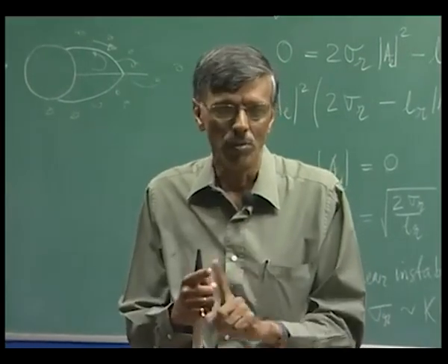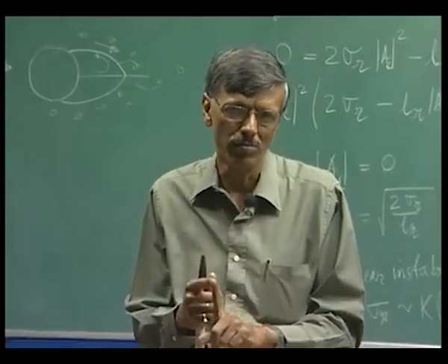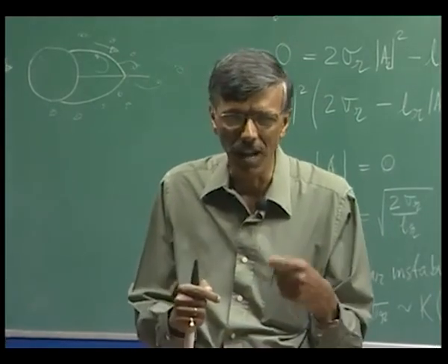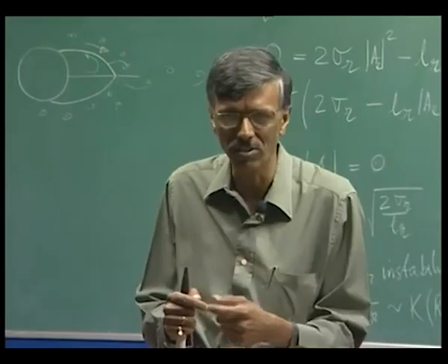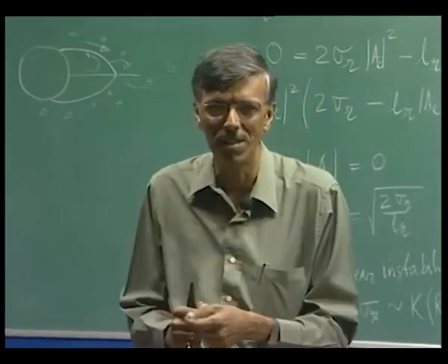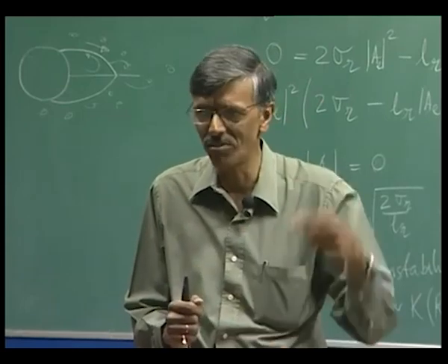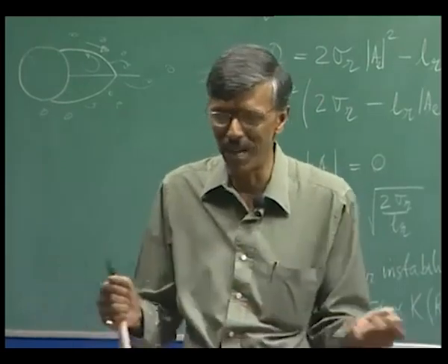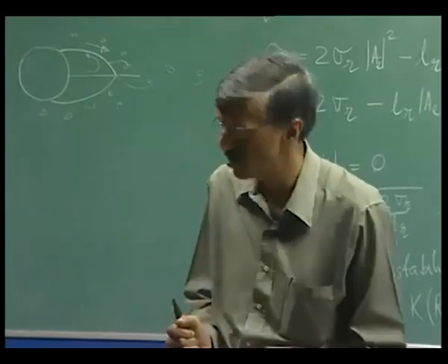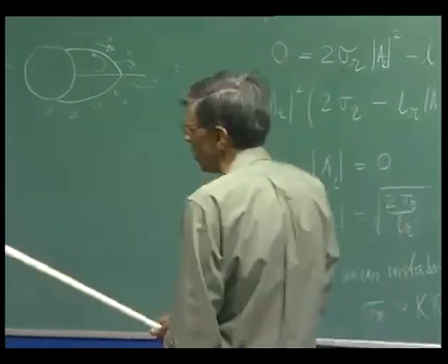Problem is two. One is, of course, the amplitude is too low. So, you would not know with reliability what it is that you are studying. And the second thing is that it is much easier to measure the frequency. I will get the oscillation, and once I have the time trace, I can do a Fourier transform and I can obtain the Strouhal number. So, this is what we are talking about.